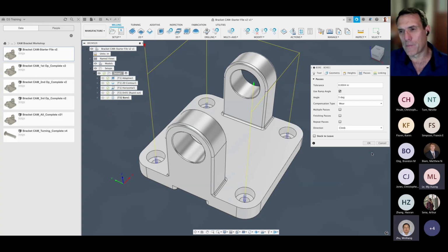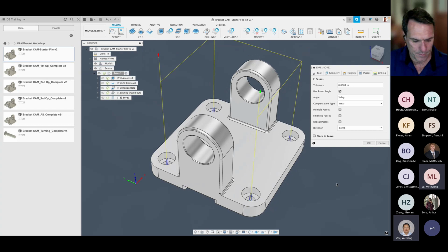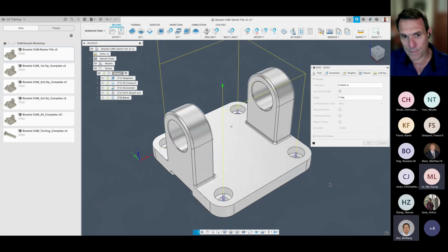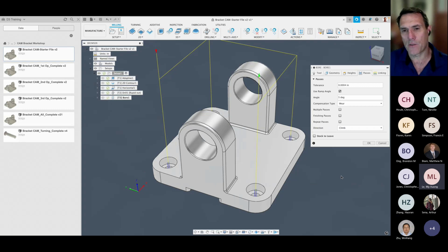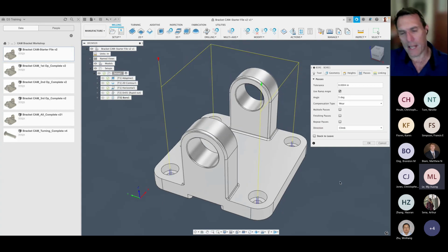So how does it know? Is this information passed through the post processor? Yes, that information is passed through the post processor to the CNC machine, in a case where you're going to have a machine where compensation is valuable. The G code, I think it was G42, prompts the machine to take a look at what its values are.